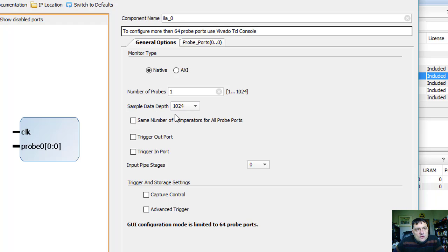The memory is coming from onboard memory in the fabric of the FPGA, what they call block RAMs. There are static RAMs that are available. They're scattered throughout the fabric of the FPGA, or it's going to use the flip-flops that are built into the logic cells of the FPGA. We don't really have a whole lot of configuration control over that, but certainly the more memory that I'm using for the ILA, the less memory I would have for a design. For these very simple designs, it's hard to imagine that there would ever be memory pressure. But as your designs start to get larger and you start to use those block RAMs for things, this does become a limitation.